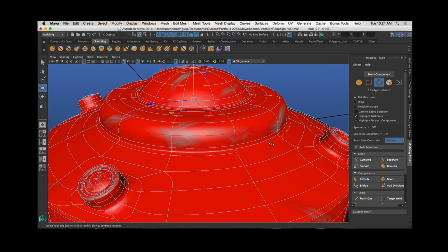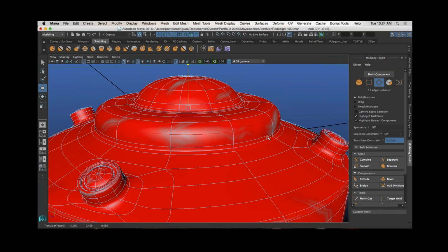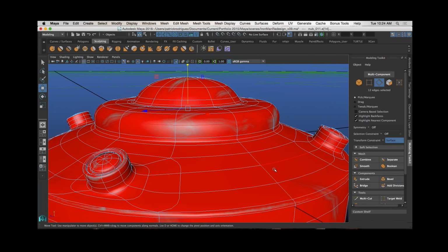Now you're looking at it and saying, well, that's cool, but if you really are going to make a little bit of changes here and there after the fact, I can see that all of your textures are stretching, okay? And that's no good. So what we can also do is turn on, let's see here, what's it called? It's called Preserve UVs. So right now I'm holding down Shift and Command, and I'm right-clicking, and I can turn on Preserve UVs. So now I'm just showing you that it's checked on already.